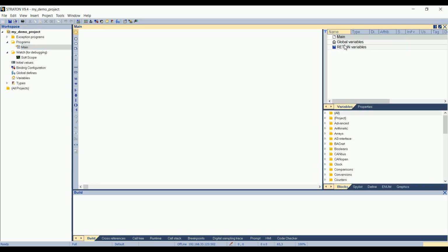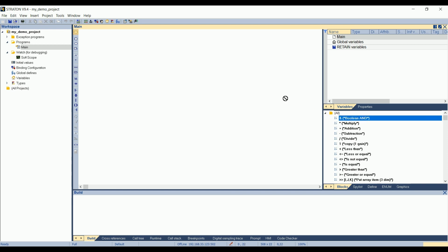On the right side here, there is the variable dictionary of the available variables for this program. There is also here a list of blocks. To add a block, select it and then drag and drop it in the program window. For example, here I added the end block. As the variables are not specified yet, they are filled with question marks.